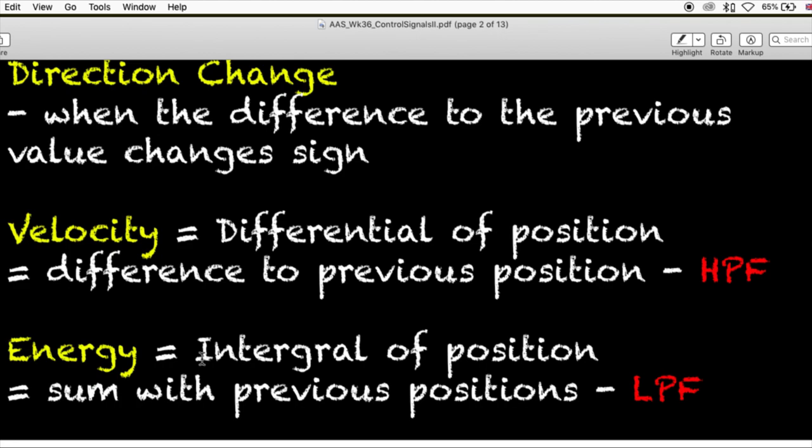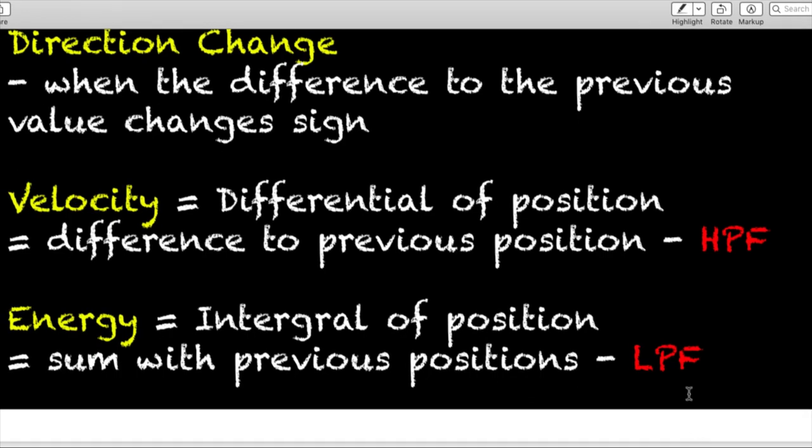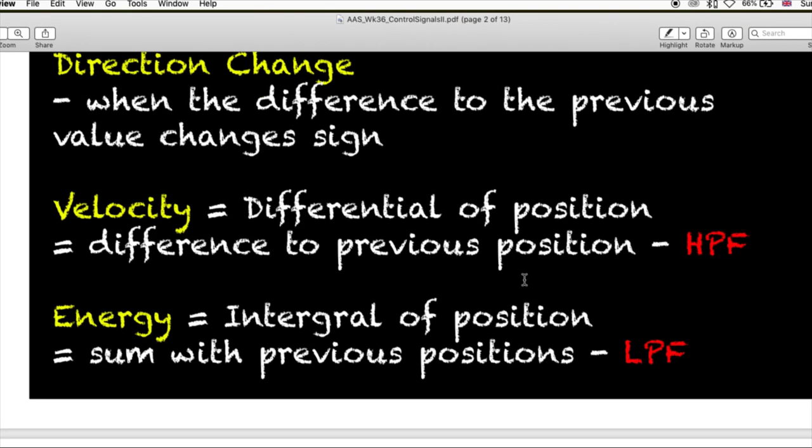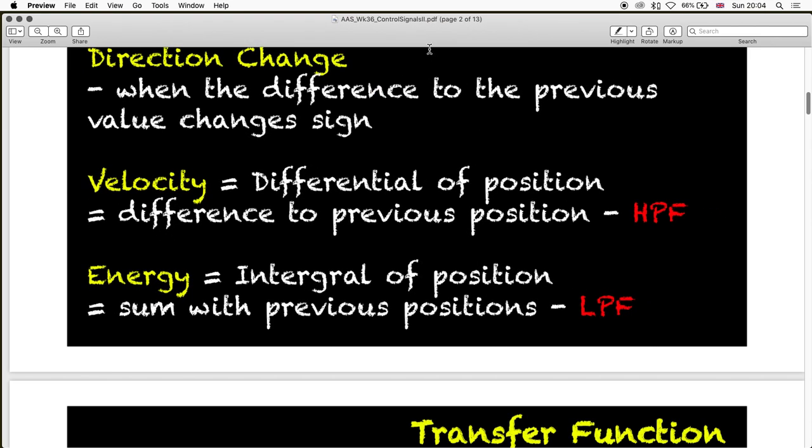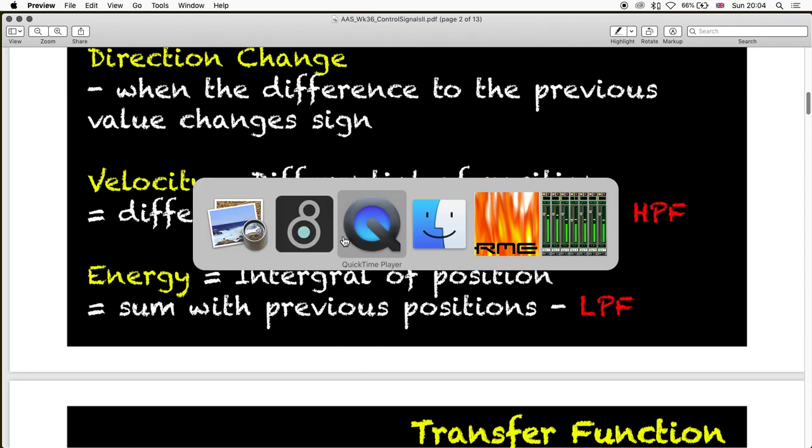If you have a bipolar signal without DC offset, then the growth will be capped. You won't get an explosion like that. So we'll look at that, and then to make the connection to audio signal processing, actually taking the integral, integrating a signal, is low-pass filtering it. Okay, so let's look at these implementations then.